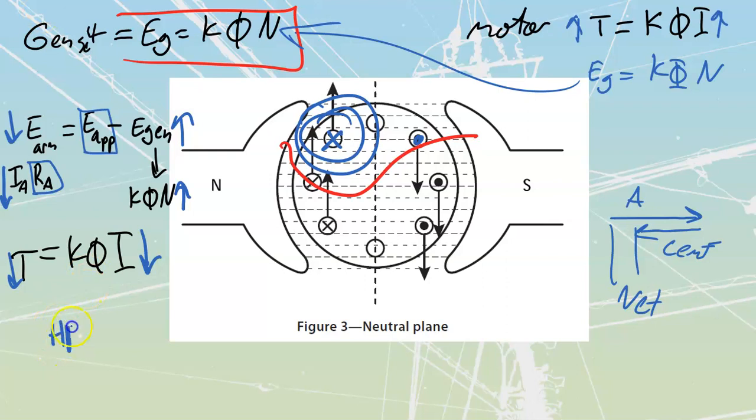This is horsepower. They don't have it in front of there, they're missing it from the front, is equal to my torque times my rotation, my RPM, all over top of this constant of 5252. I'm not going to go through all the math that they took to get these steps because they're just showing you all the steps that it takes to get there.